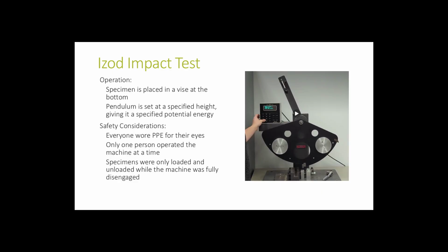The safety considerations we made were that everyone wore personal protective equipment for their eyes. Only one person was allowed to operate the machine at a time, with others staying at least a distance of 5 feet away. And the specimens were only loaded and unloaded when the pendulum was fully unlatched and resting at the bottom.